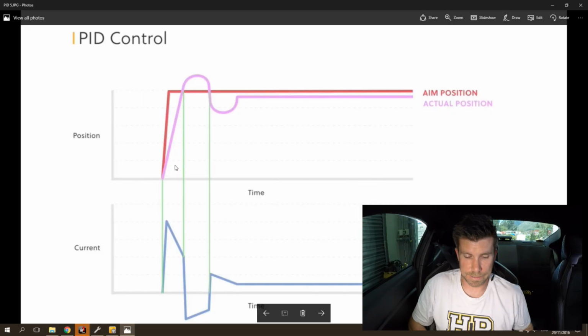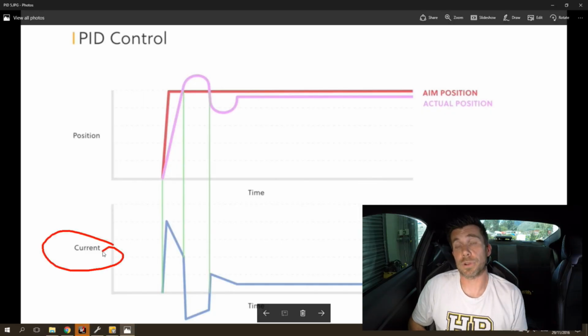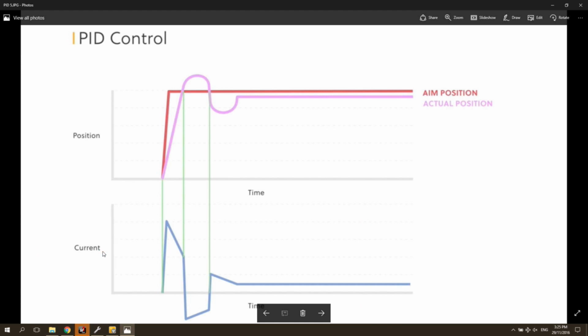And what we're looking at here is the current being sent to a drive-by-wire throttle control motor. So in the case of a DC drive-by-wire throttle motor, the ECU is able to drive the DC motor both forwards and backwards. So we have a 0 point in our axis here, and we can see that we have the motor being driven both above and also below our axis there.